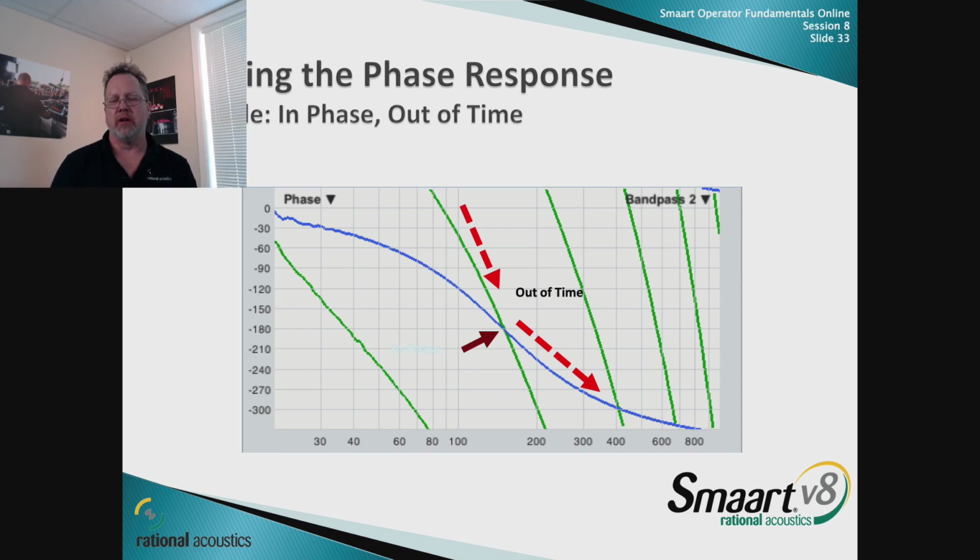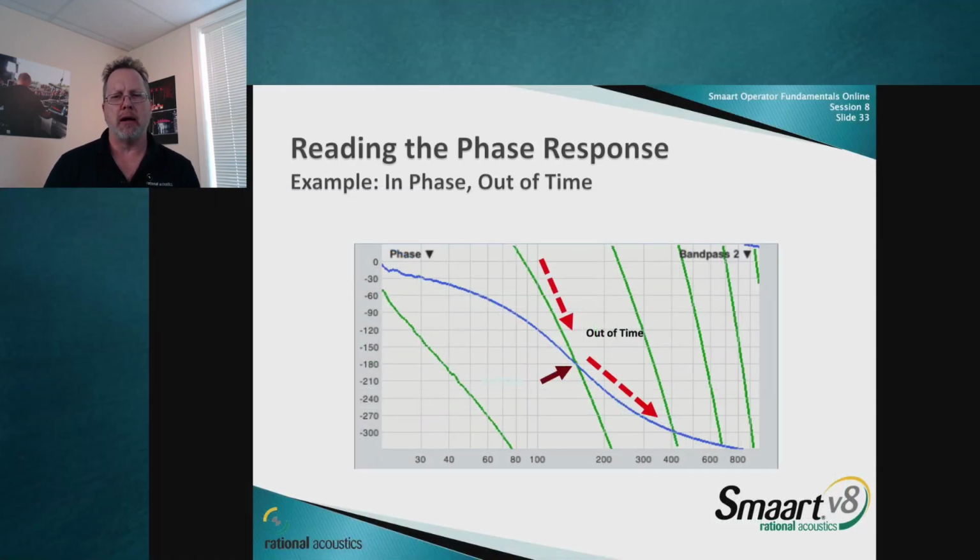A classic one is, I've got to set the timing for my sub to main. That's going to be a subject of, I think, not this Friday, but next Friday. Don't know which one, but that's the classic question. I need to time my subs to my mains. That's because while most of us don't have to do a crossover between mids and highs in our main system, we normally rely on the manufacturer for that. The one crossover we do have to time quite often is timing mains to the subs.